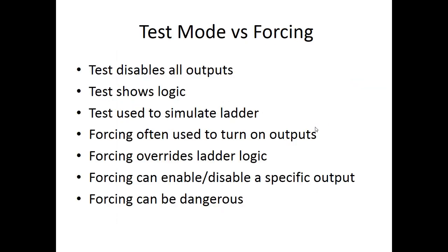We did test modes versus forcing. Test disabled all the outputs. The test showed your logic being true. It was solving your logic for you, which is useful to see if you were thinking like you should, so you could simulate your ladder, but it actually didn't fire the outputs.